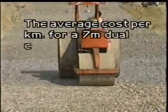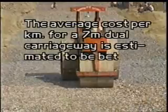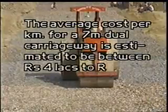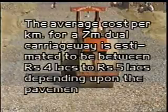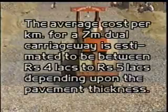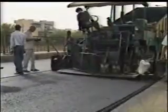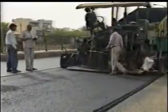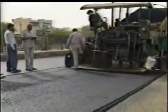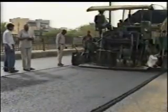The average cost per kilometer for a 7-meter wide dual carriageway is estimated to be between rupees 4 to 5 lakhs depending upon the pavement thickness. The pavement, designed and constructed on scientific basis, will provide comfort to passengers in addition to providing durability and reduced vehicle operation cost.